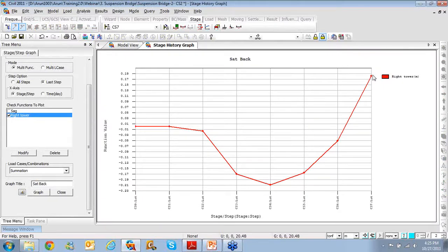At the beginning of construction stage, again it is the backward construction stage. Direction is from the left side towards the right side. So this is the final state and this will be the initial state. This is how much from the zero level the camber should be provided for the vertical pylon, and this is how the deformation will occur, and then it will converge, and by the end of the construction you will get a perfectly aligned absolute zero value and a straight pylon as desired.